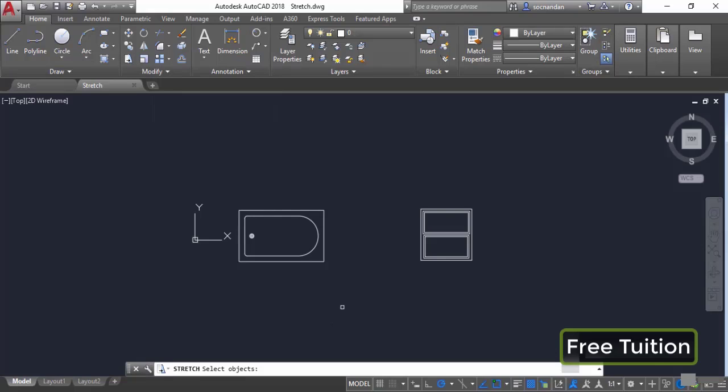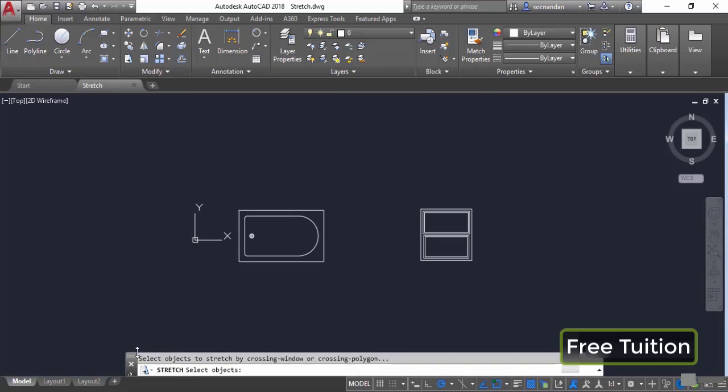But in this case, you need to select objects in a very specific way, and if you expand this command line, you'll notice that it's also prompting you to select it with only crossing window or crossing polygon. So now in order to make a crossing window, I'll click on the right side and I'll move my cursor towards left, just like this, and here we have this crossing window with dashed boundaries. Now in this case also I'm not selecting the complete bathtub. Instead I'm selecting it only partially.